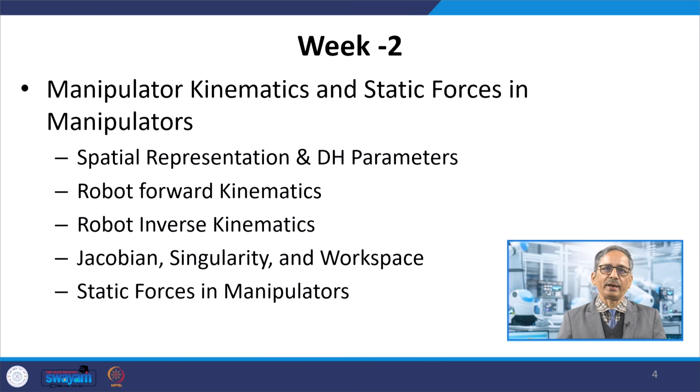Next week, that is week 2, is dedicated to manipulator kinematics and static forces in manipulators. Essentially, first we are going to see how we can represent a manipulator mathematically. So here comes the spatial representation and DH parameters. Then we are going to see the forward kinematics and the inverse kinematics of manipulators using examples. Then we will come to the concept of Jacobian, singularity and the workspace, and at the latter part of this week we will be studying static forces in manipulators.